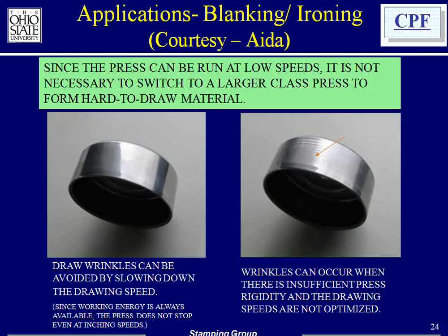And you might ask, why is the speed so important? During the formation, you generate heat because the mechanical energy you put into the formation turns into heat, and this heat is especially important at the interface between the die and the material, and that affects the lubrication. So unless you have some pressure additives, which usually you do, and temperature additives that make the lubricant pretty effective, you may have problems because of high speed during friction because the interface temperature is high.